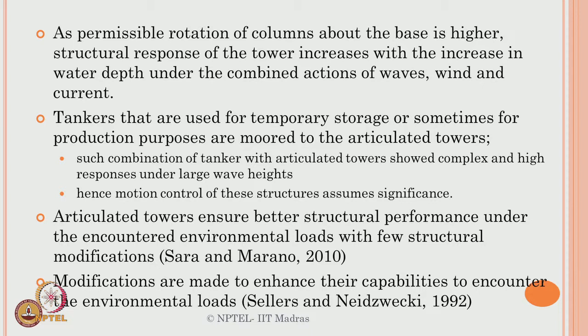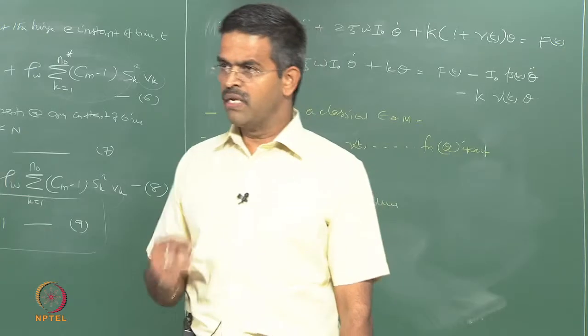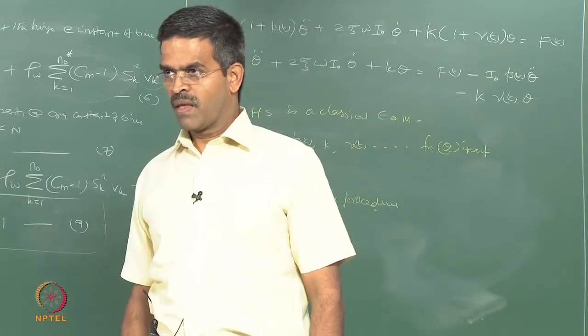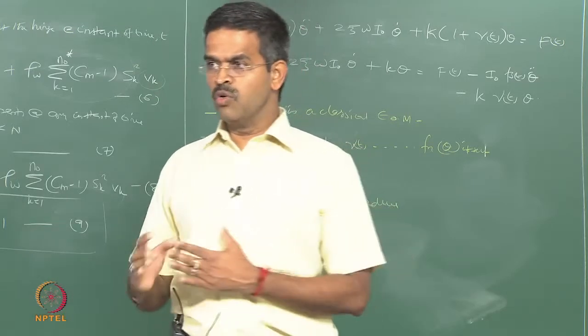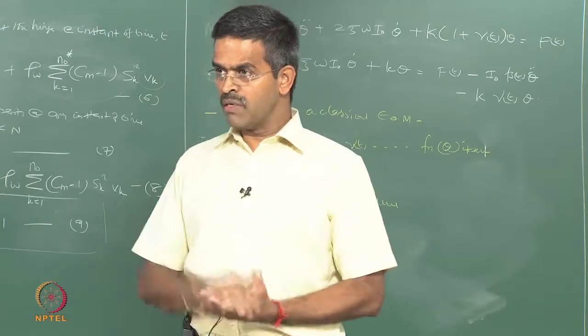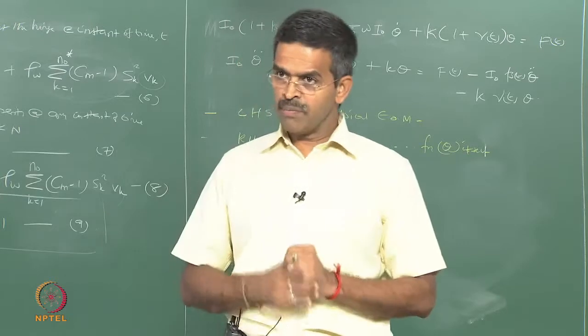And when you are using this as a combination of a tanker with articulated towers, they showed complex and high responses under large wave heights, because now the moment you start using it as a production platform, it will be used for larger wave heights as well. Okay. So, when you go for larger wave heights or greater water depths, they showed higher responses. Therefore, motion control became a significant concept in the early 90s for offshore structures, when people desired to continue with the MLAT as one of the suitable alternatives for medium water depths for exploration and production.